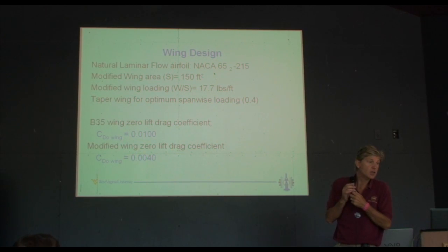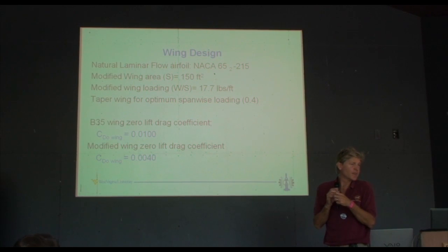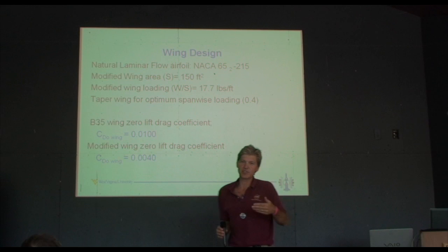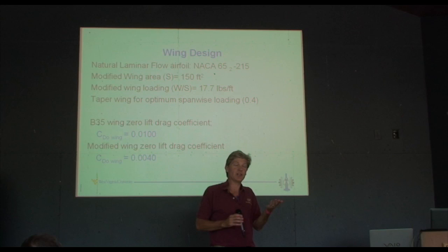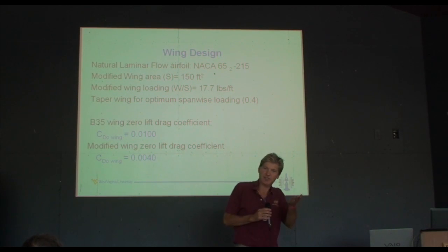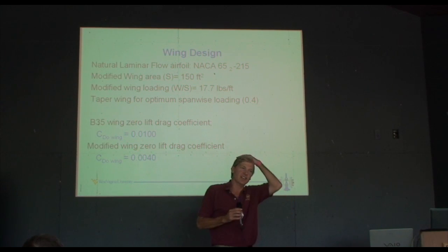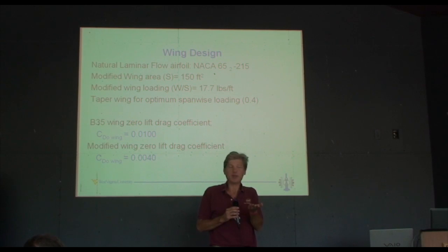This is a balanced airfoil. Also, it doesn't build up pitching moment. This one here. Right. Like some of the laminar ones. Yeah, the laminar ones have pitching moments that get out of hand. Right. I thought the pitching moment ought to be under 0.25. Yeah. And I know some of those are like 0.40. If you get into what we're talking about, some of these airfoils have pitching moments as well as lift and drag. This kind of gets into fairly advanced levels of airfoil design. And some of these airfoils can have rather peculiar pitching moment properties.